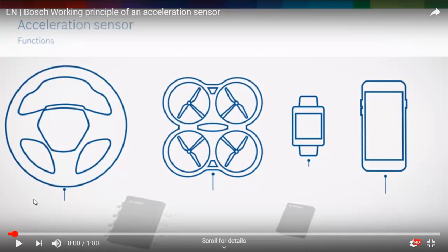While on the other hand, if you want a very precise accelerometer to be used, for example, in games, then you turn on the precise accelerometer, which also consumes a lot more power. In all sensors, you have this typical trade-off between power consumption and precision. In cheap phones, you use just one and try to find a trade-off between the two.